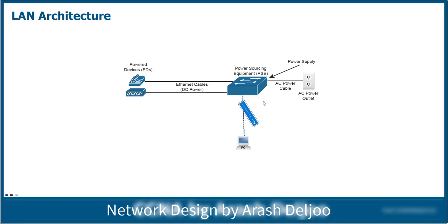This is so important. I'm going to talk about this operation. Look here. When you connect a device to a port of the PoE-capable switch, or the PSE, first we should have a negotiation between these two devices. After the negotiation, the switch can understand whether it should apply power to this device or not. Don't forget, if you apply power to a device that doesn't need it, it can damage the device, and this is so important. This is current more than the device needs. Because of that, first we have a negotiation between these two devices.